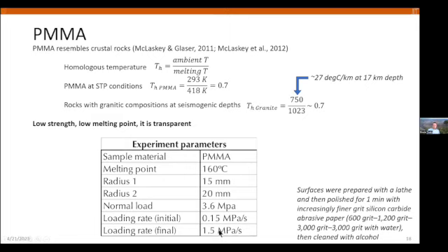In all the experiments we have been performing here, we try to prepare the surfaces in a standard way in order to minimize the differences due to sample preparation. The samples are typically prepared with a lathe, then polished with abrasive paper of different grits, and then cleaned with alcohol, which is extremely important. We had some experiments where we didn't clean the surface and the behavior was extremely different. So there is a big attention on this.